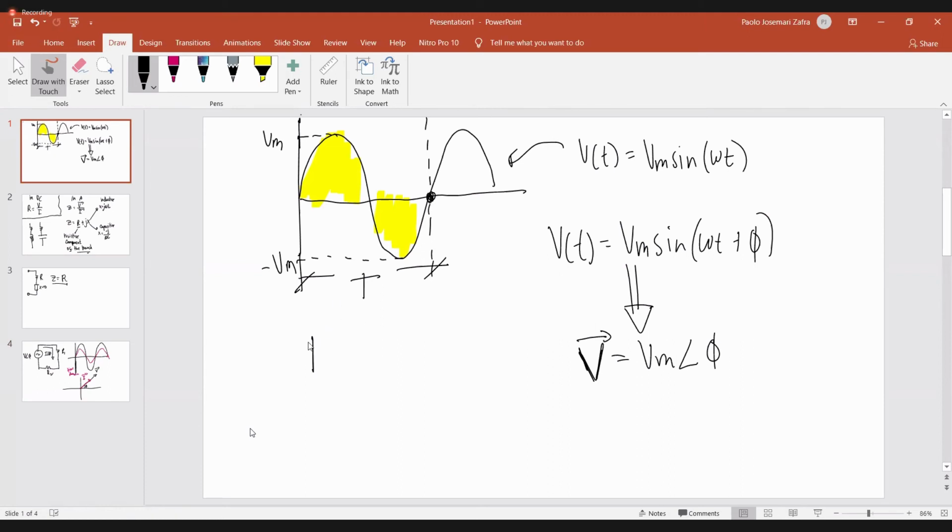So your period is equivalent to 1 over the frequency. Meaning, your frequency is 500, right? So that's just 1 over 500, or, to be precise, 2 milliseconds. I told you to start saving at this time because there is an unexplained reduction of amplitude within the first cycle in your RC circuit or in your RC experiment later on.